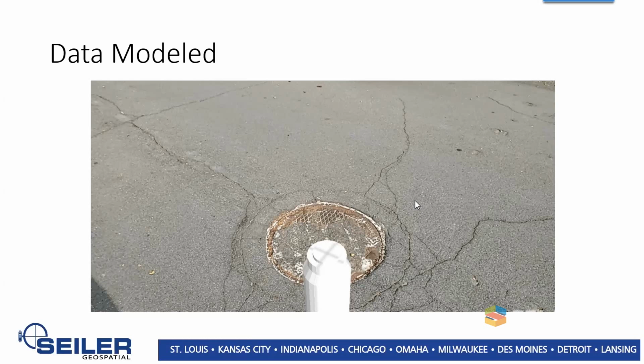You may try importing the FBX from InfraWorks to Navisworks and exporting the IFC file, or bringing that file into SketchUp or Format. Materials are always going to be a problem. You seem to lose some materials if they have a weird name, so you may have to add new materials to an item, but you could try that route.